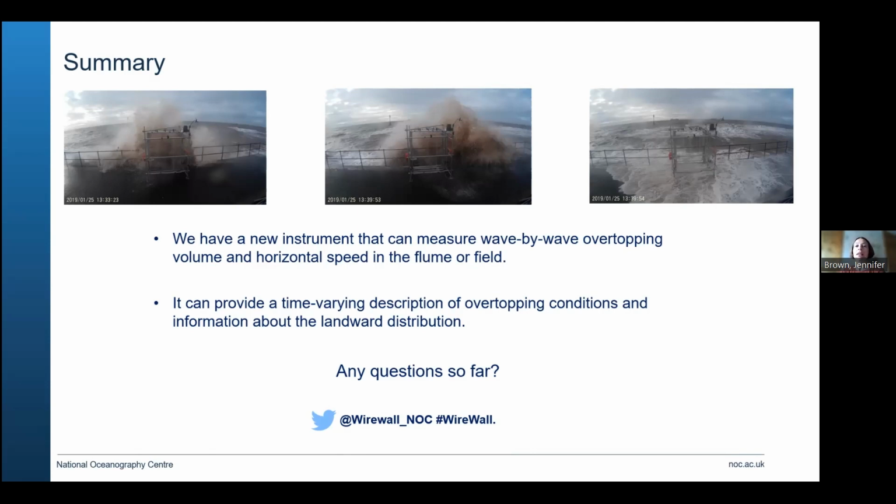Some people are also using LiDAR to look at wave overtopping, but that only measures the solid water that can go over the top of a seawall because it measures depth changes, and it doesn't measure spray because it won't get the data in between the individual droplets that the wires can pick up.